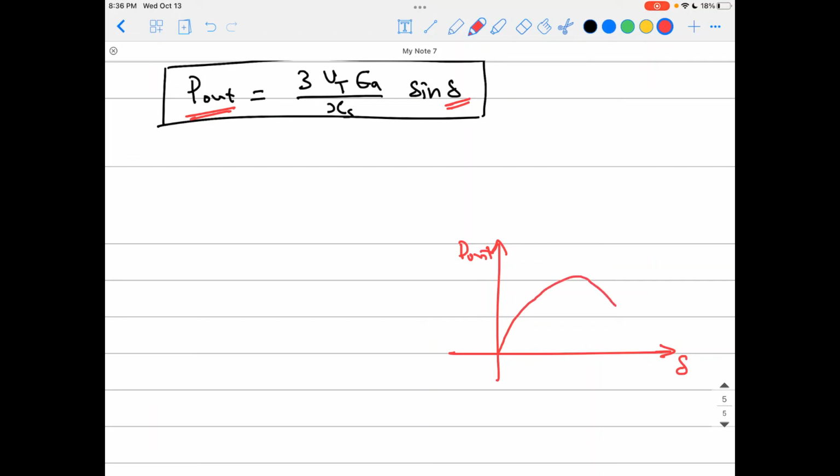Okay, we're more concerned about the positive part of the sine wave, because the negative part just means the power connection is reversed, and this is not happening in a generator. That means we're talking about a motor, because the electric power is reversed in direction, coming into the machine. It's not a generator anymore, it's a motor, and we cannot permit this to happen. In a typical machine, it's not working like that, and we even have a protection we call reverse power protection over the synchronous generator to make sure this will never happen, because it will damage the machine and even cause a catastrophe.